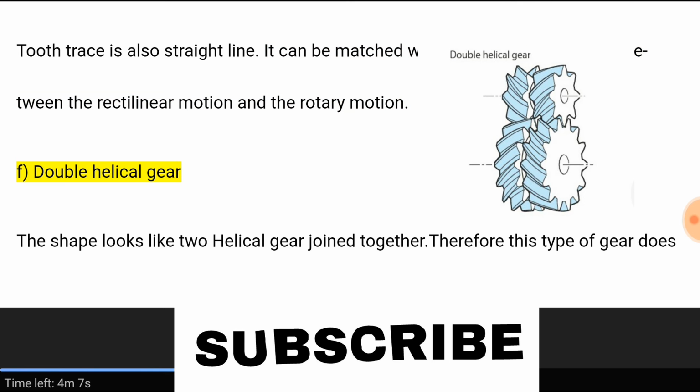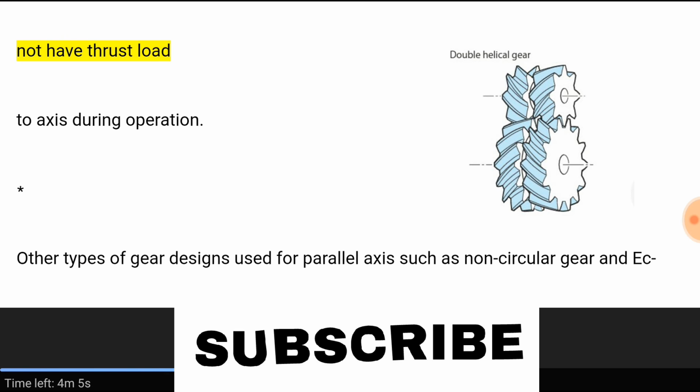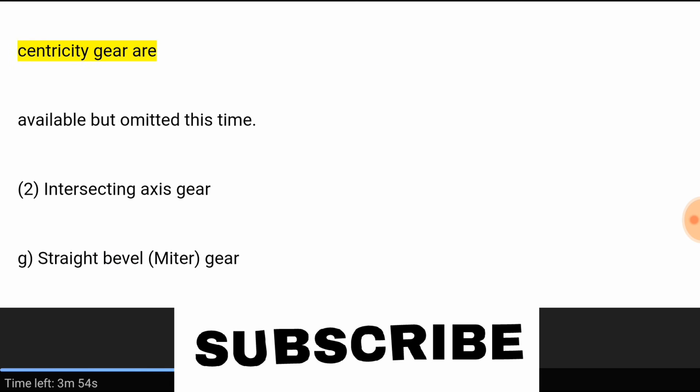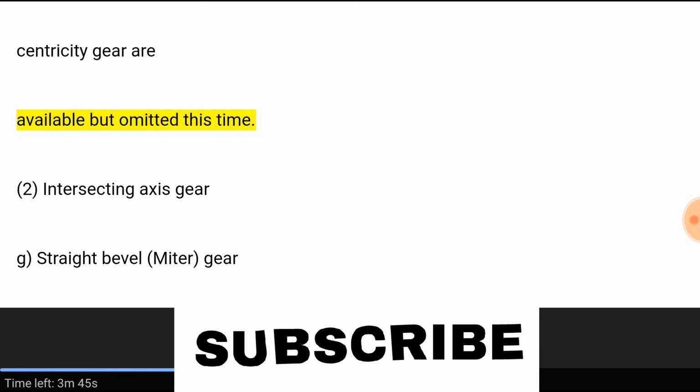F. Double helical gear. The shape looks like two helical gears joined together. Therefore, this type of gear does not have thrust load to axis during operation. Other types of gear designs used for parallel axis, such as non-circular gear and eccentricity gear, are available but omitted this time. 2. Intersecting axis gear.